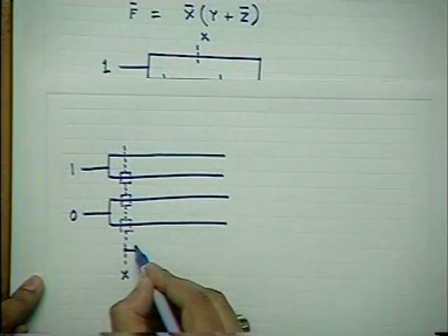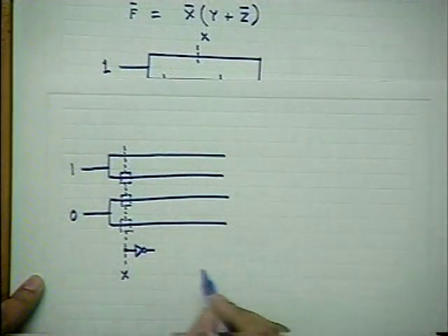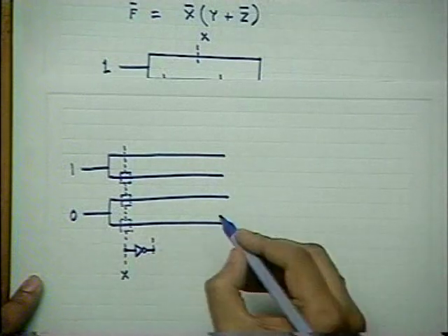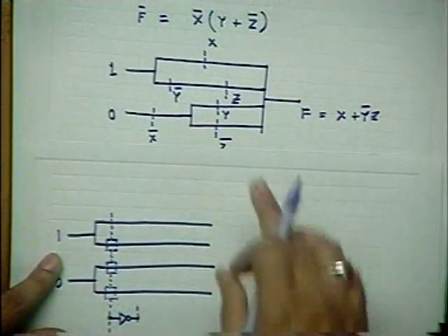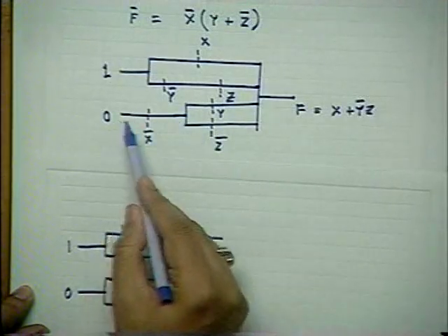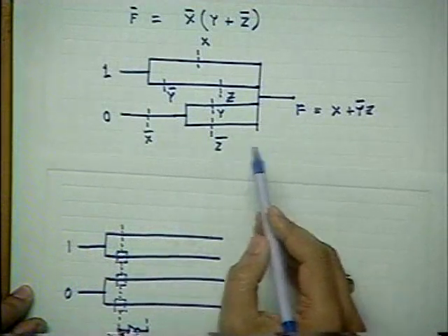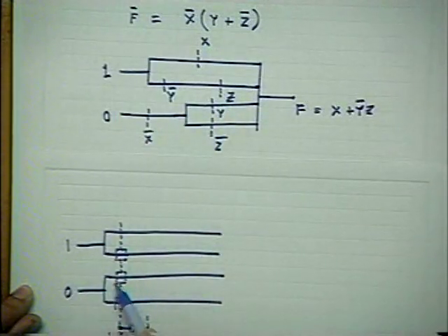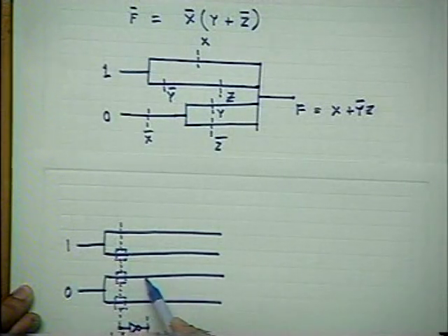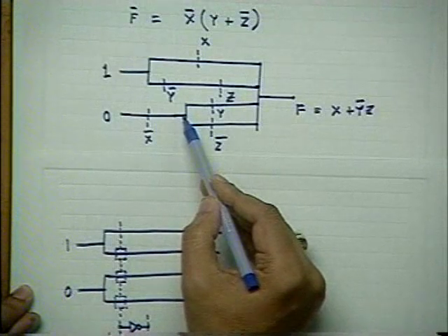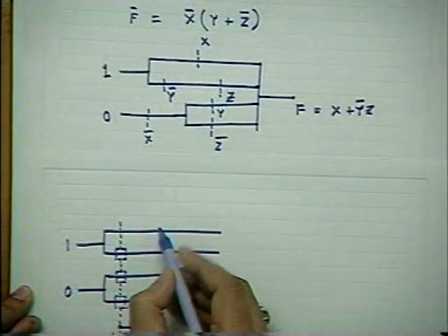Thereafter, I told you that always at the input I have some inverters to produce both the function x and x bar. So automatically at this point x bar and x complement will be produced. Now what is needed in this circuit? I need that x bar is to be applied at a 0, the diffusion lines carrying 0, and it is in series with this parallel combination. Because here in the 0, I use 4 diffusion lines, I will put a transistor here and here both, so that it is equivalently 1 transistor on this single line. Whereas I will not put any transistor here. So what I will do is simply this.